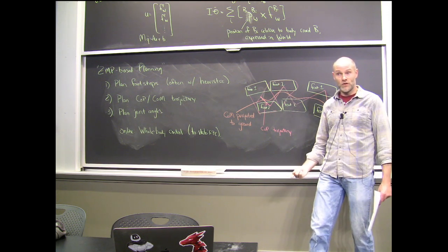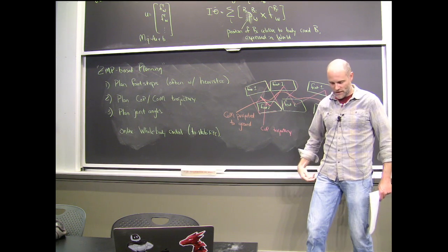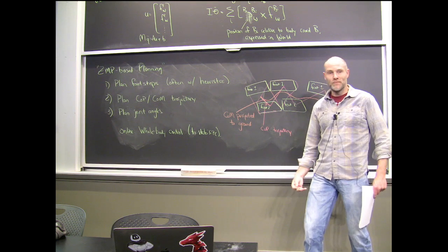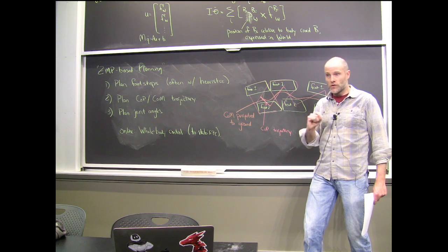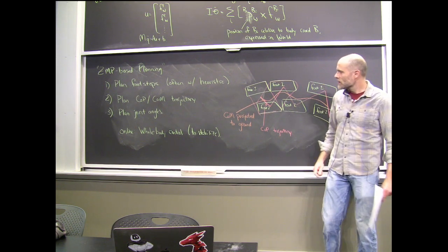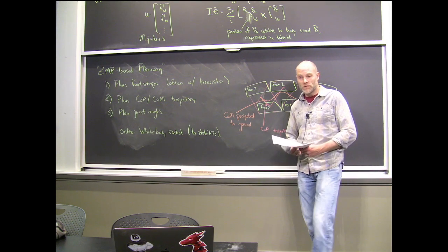That's my swing leg trajectory. And then once I've got that swing leg trajectory, now I can find the joint angles of all my other parts to make my center of mass follow the desired trajectory. And those are all small kinematics problems to solve. When you're done, though, you can do whole body control to make the whole thing work.